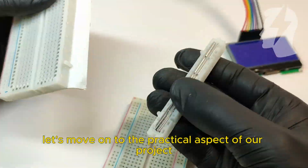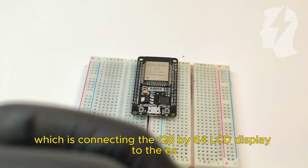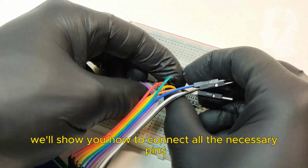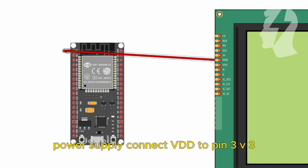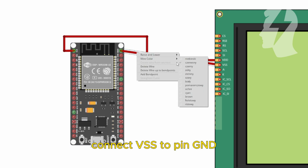Now let's move on to the practical aspect of our project, which is connecting the 128 by 64 LCD display to the ESP32. In this step, we'll show you how to connect all the necessary pins step by step to facilitate the visualization of the process. Power supply. Connect VDD to pin 3V3. Connect VSS to pin GND.